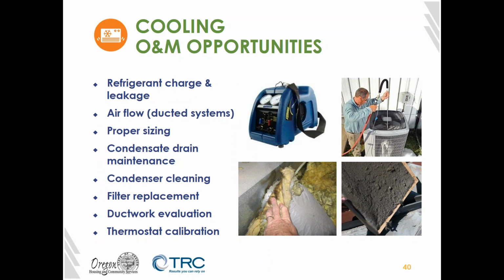You know, it really depends, because you should basically focus on wherever the biggest leaks are. And it's going to vary by building. The order that I presented things in, sealing the top of the building, and then sealing the bottom of the building, and then sealing vertical shafts, and then sealing the sides of the building, that's like a general approach, because particularly in heating dominated climates, a lot of leakage tends to happen at the top of the building.